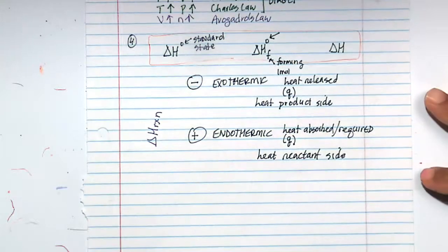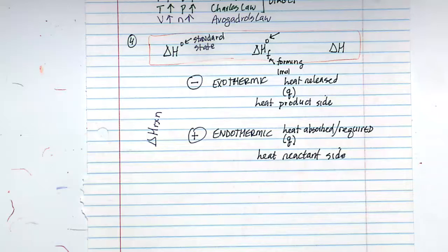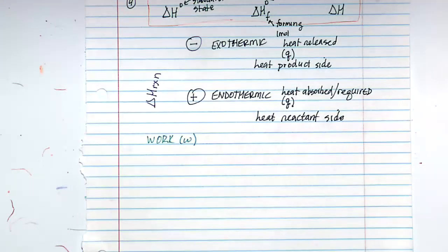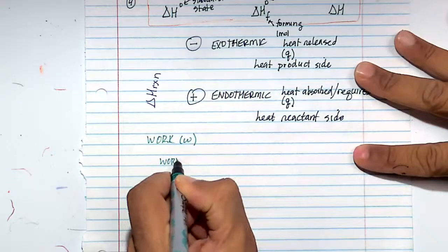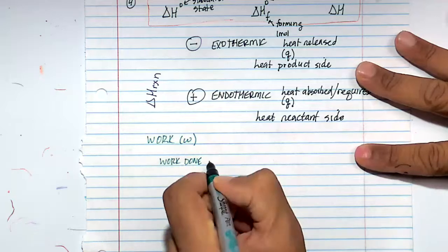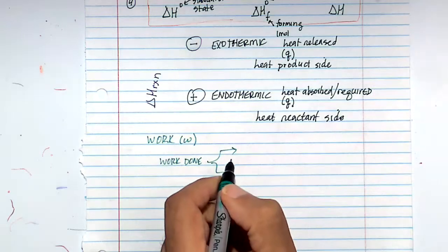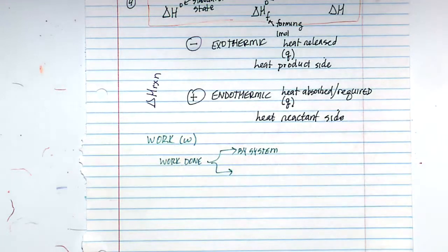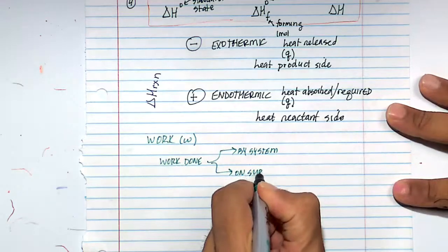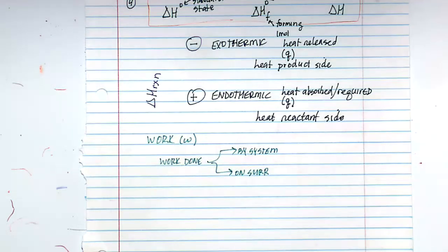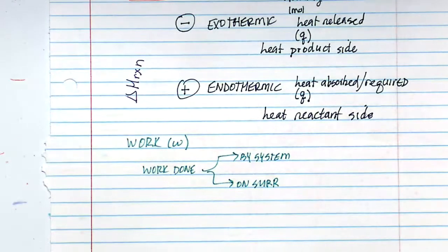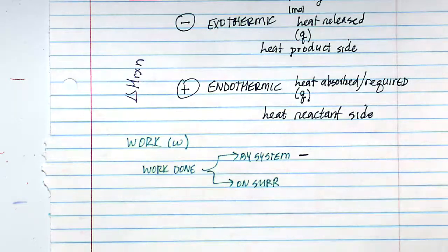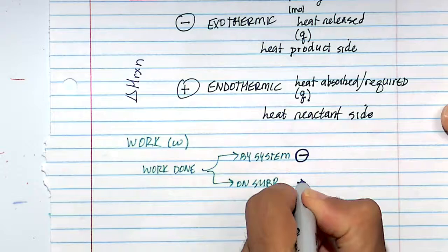So we have heat, Q. We also have another form of energy that's kind of useful, and we're going to call that work. Here we have signage also, but you've got to look at the wording. Here it's work done by me, so I'll say by the system, on you guys. You guys are my universe, the surroundings. So in this case, the system will have a negative sign for work. They're both energies, work and heat Q, but this is energy that is useful. So that's going to be a negative sign, and the surroundings, same value but opposite sign.